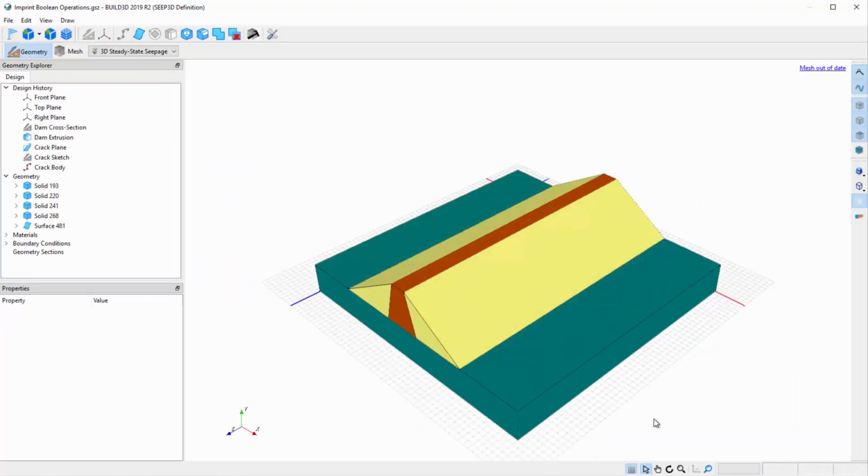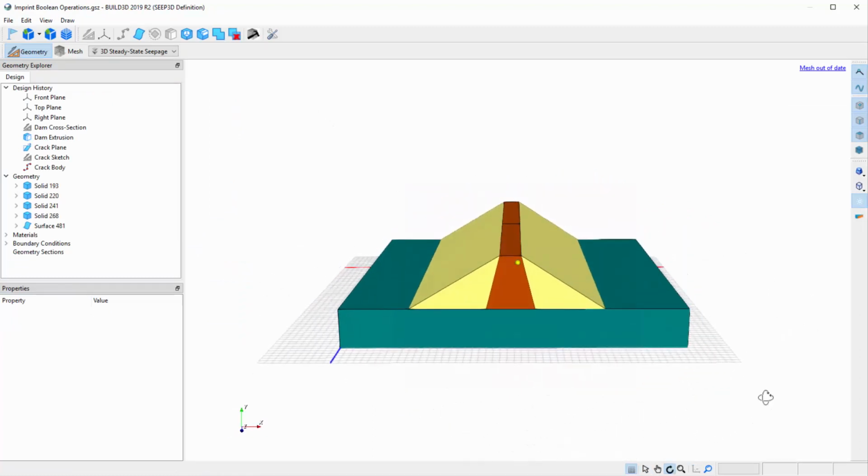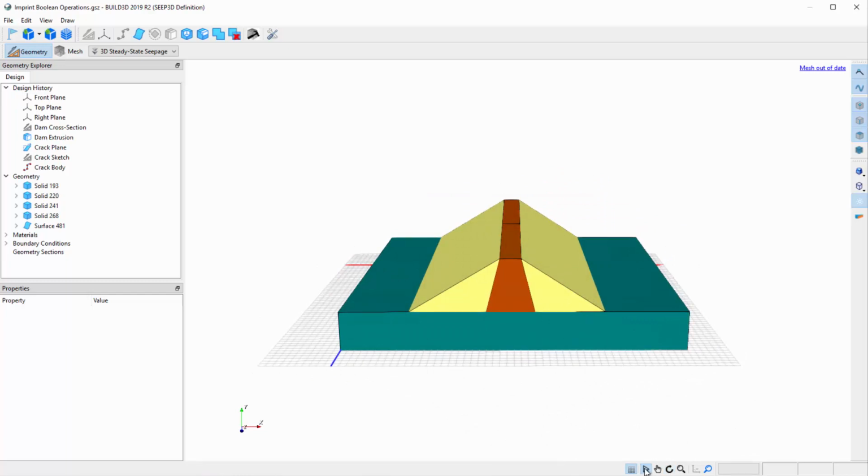In some cases, boundary conditions are only applied to a portion of a three-dimensional surface. Under normal conditions, dams are operated to have a certain amount of freeboard such that the reservoir level is not at or near the dam crest. In this case, the reservoir is at an elevation of 12 meters. Consequently, we need to divide the upstream dam face into two sections such that the reservoir boundary condition is only applied to the appropriate elements. To do so, we will generate a surface representing the water level in the reservoir.